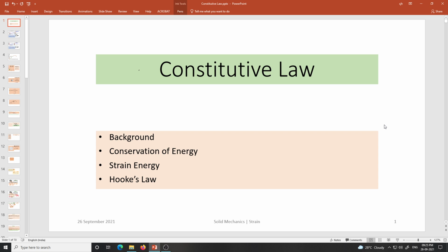Now, as you recall, in the first lecture when we introduced the concept of stresses, we talked about the continuum body. That means the three-dimensional body where the material is distributed uniformly over the entire body of interest or the domain of interest. And we assume the continuous distribution of matter. We did not respect the crystalline structure or the molecular structure or the discrete nature of the body. Same thing we have done in the case of the strains when we learned the strains.